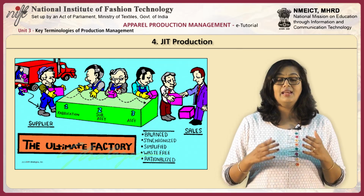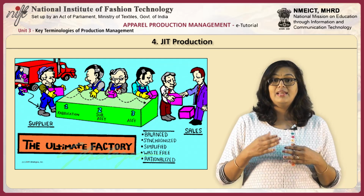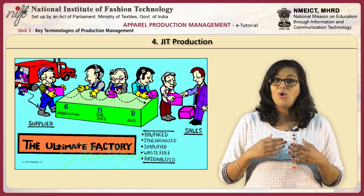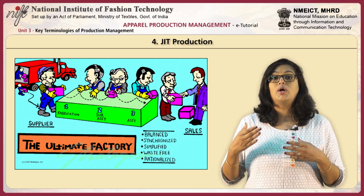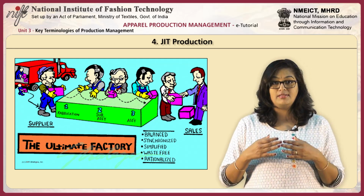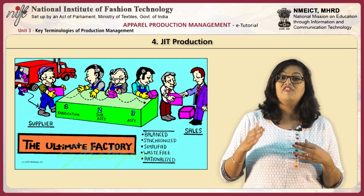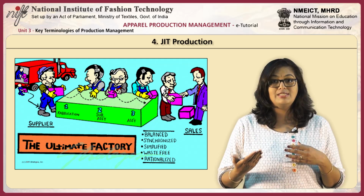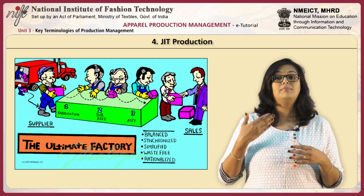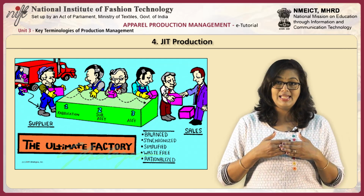Here we can see an ideal example of JIT production, wherein there is absolutely no gap or delay in time or stocking of pieces or warehousing of any production components. The supplier processes into fabrication. From fabrication it moves on to sub-assembly. From sub-assembly it moves on to assembly. And finally it directly goes on to sales.